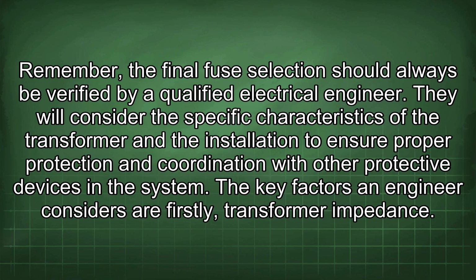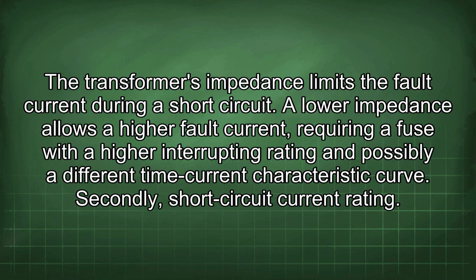Remember, the final fuse selection should always be verified by a qualified electrical engineer. They will consider the specific characteristics of the transformer and the installation to ensure proper protection and coordination with other protective devices in the system. The key factors an engineer considers are firstly transformer impedance. The transformer's impedance limits the fault current during a short circuit.